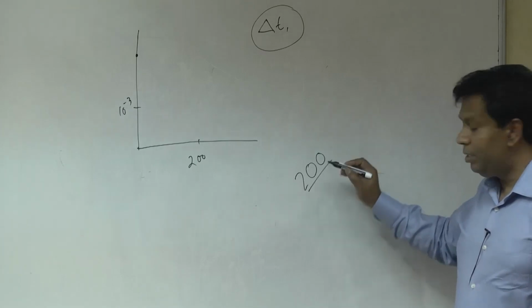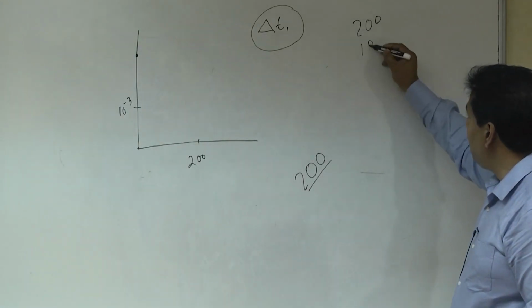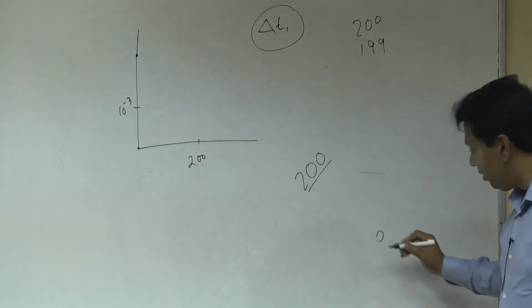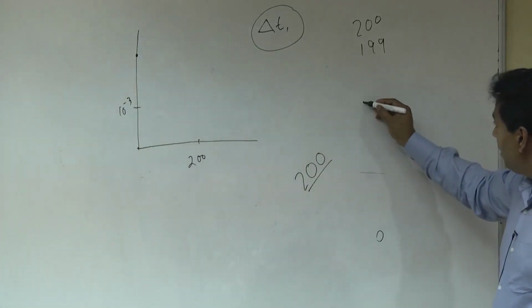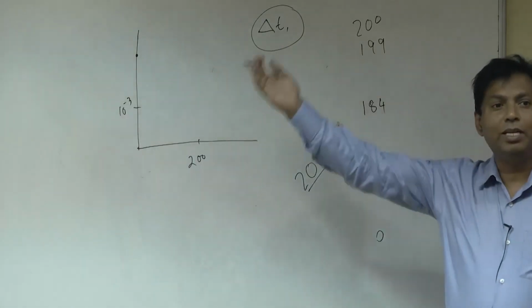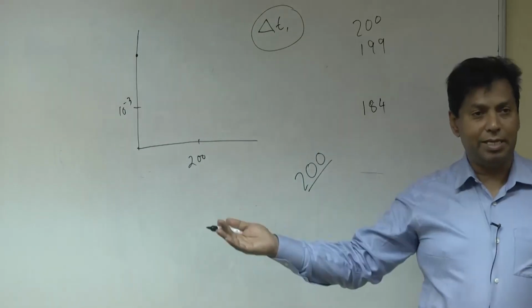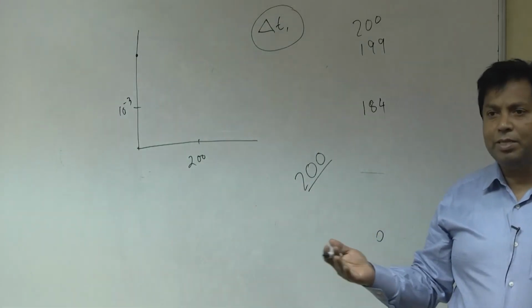When the simulation starts, it starts with 200, 199, it's coming down. So be careful, it is not up to 0. Mostly I saw this computer converging at about 184 or 183, then going to the next time step. So the time step is called the outer iteration. So how many time steps are we solving?